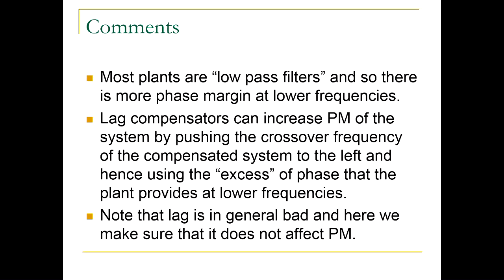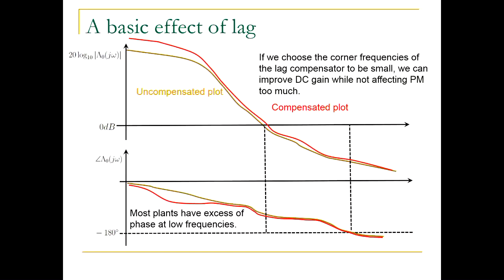In general, lag by itself is bad. It's like a delay in your system. Lag is really similar to delay, and delay is bad. So lag is typically bad, but if you use it skillfully, you can actually use it to your advantage. And you would typically try to not screw up the phase margin by using the lag, or potentially increase it if you use the technique just described above. All right, so this is one way you can use lag.